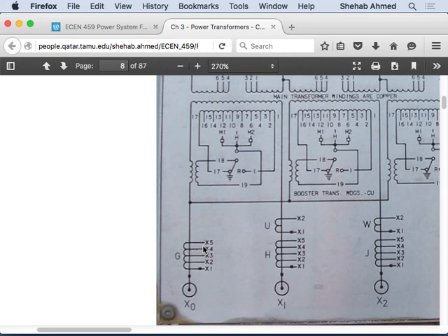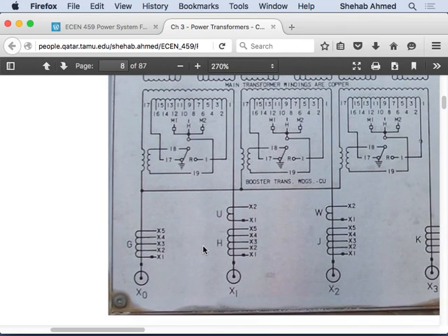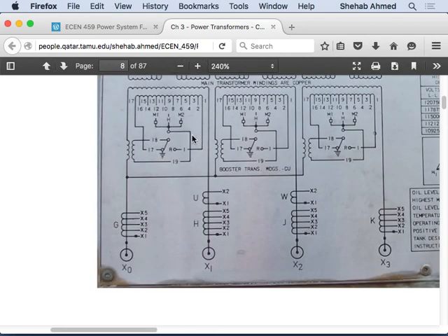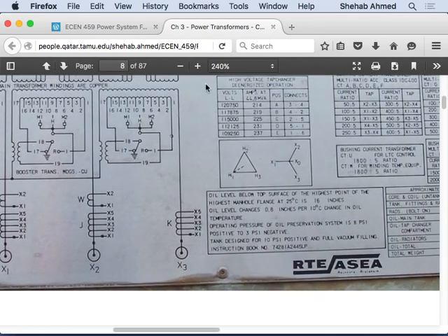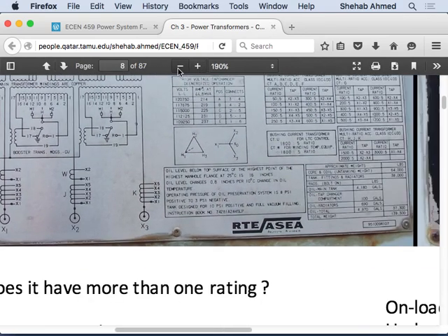If there's an unbalance in the system, or for some reason a short circuit between any of the windings and the ground, like if any of the winding insulation is bare and touching the transformer, then we want to make sure that we measure that and protect against it right away, right? So we have these current transformers and voltage transformers. Here, these are voltage transformers probably, yeah. So you'd sometimes have the protection devices installed on the device itself.